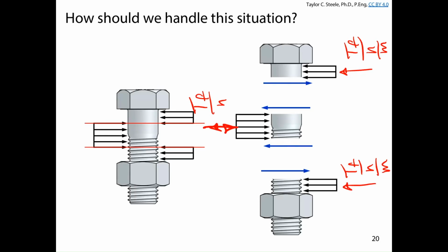If we just turn it 90 degrees, we can think of this as a point load in the middle, and we've got a couple of reactions out here. Well, if we're going to apply a load to this beam, and the strength of the support over here is, let's just say, 70% of whatever the strength is, let's just say VR, and this one is VR. We've got a resistance of one side and the resistance of the other side. It doesn't really matter when this one is going to fail versus that one. It just means that as soon as we get to a total load of 1.4 VR on the beam, we're going to fail the support here, right?